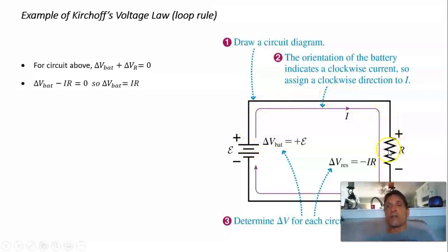So this is a user of power, and this is a generator of power. Okay, so this is just applying Kirchhoff's voltage law. And so if we pick the direction of the current, we choose to go around the loop in that direction, which we always should do in the course. That means that this delta V across any resistor is negative IR.